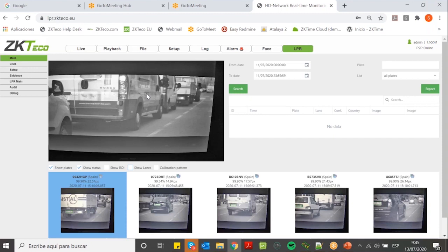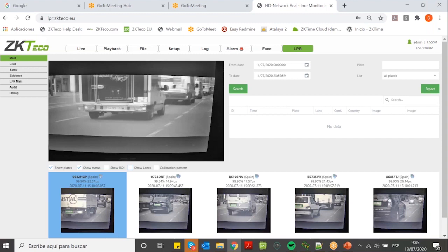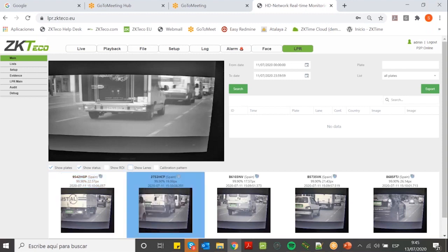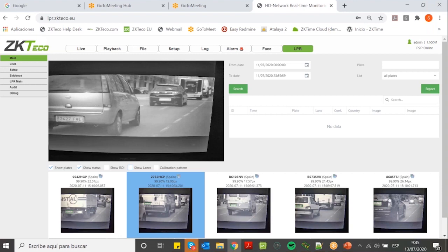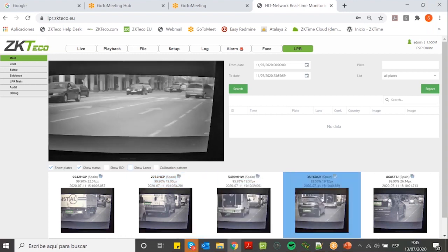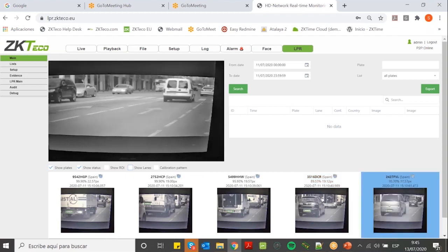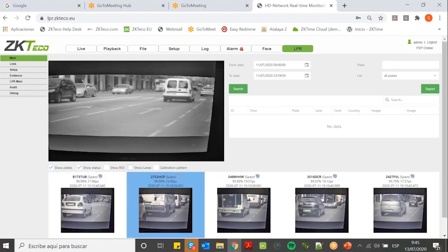the camera can catch. For sure, you need to respect the distance from the camera to the car, up to around 15-20 meters, and the other thing you need to respect is the speed of the car, around 20 kilometers per hour. But you can see in this demonstration the cars are going so fast. But the recommendation is to use up to 20 kilometers per hour.